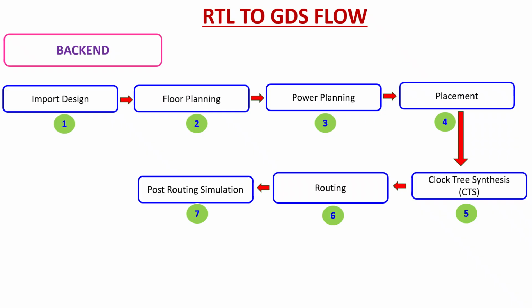post-routing simulation. In this post-routing simulation, the output we get after the routing must be equal to the output we got after the post-synthesis simulation and in the RTL simulation. Here, the timing analysis is performed after routing to check the setup and hold violation considering wire delays.